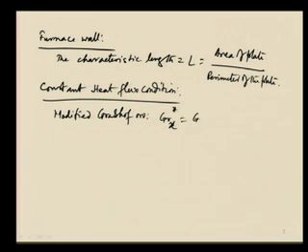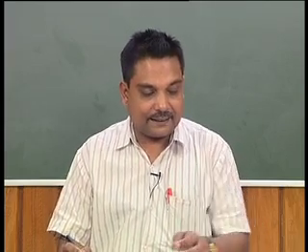This is written as the normal Grashof number multiplied by the Nusselt number, where the Nusselt number is based on the heat flux condition. So it is g beta q_w x to the power 4 divided by k, the thermal conductivity, into nu squared, the momentum diffusivity, where q_w is the heat flux, which is constant. We can understand that the expression of the Grashof number is a little different in this case, and therefore it is called a modified Grashof number, used for constant heat flux condition.